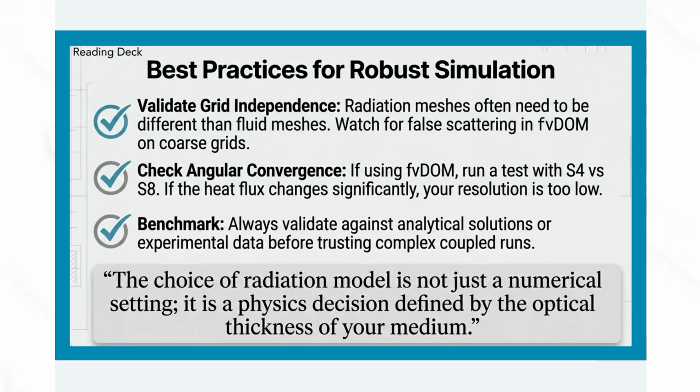Second is angular convergence. If you are paying the cost of FVDOM at all, then ensure that you are actually getting the accuracy you paid for. Run a very simple sensitivity study. Compare a simulation using S4, which is low resolution with 24 directions, and check this against S8 with higher resolution. If your heat flux results change significantly between the two runs, your initial resolution was too low.